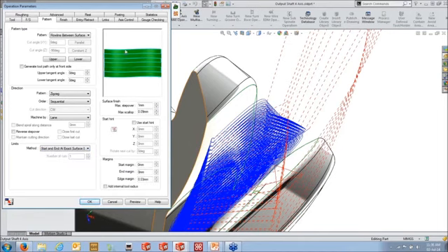Now this normally would cause you a lot of issues because sometimes your toolpath might not actually jump on the surface. It might jump on and off the surface here, causing a lot of link moves. That's where you can actually use the margins. But those margin settings down here only apply when you use the start and end at exact surface edges. You'll see if I avoid cuts at exact edges, those options are grayed out. So these are basically controlling where it actually generates.